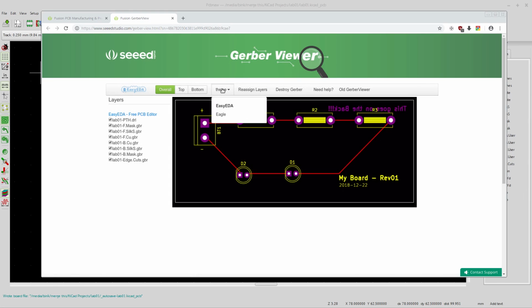We'll change the theme to, okay, whatever. It's going to be easy, EDA, or Eagle. Okay, so that's fine. And that's it, right? So now you could look at this and see that it looks right. If some piece is not connected or something went haywire, then you didn't do something right. If you're missing a bunch of holes, if the holes aren't there, or if the footprints are there, then somehow you didn't export or plot the Gerbers out right. You see? So that's good.